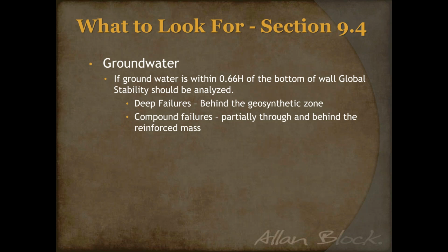So when you do see groundwater within 66% of the height of the wall, below the wall, you should look to see if you've got global stability concerns, first deep failures and also compound failures, because it could be both. It's always good to check.